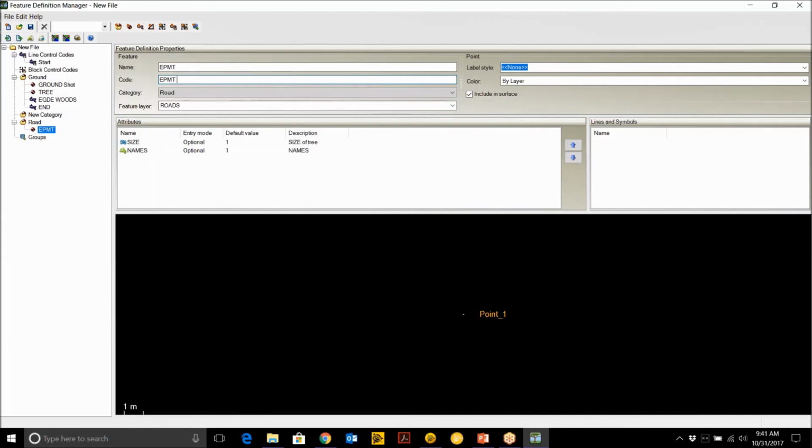Okay. And so you would number your edge of pavements as you showed there. So you would have edge of pavement 1 would be one side of the road, and then so that the software doesn't get confused between one side of the road and the other, you would name that second one 2. Correct. So would the 2 be edge of pavement space 2, or would it be all congruent and then space ST? Right. Just keep it running together like that. So 2 and then space ST.